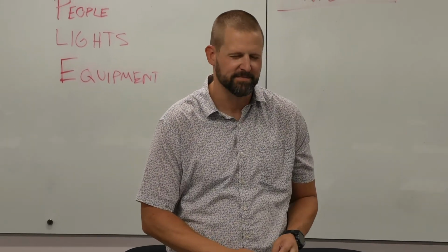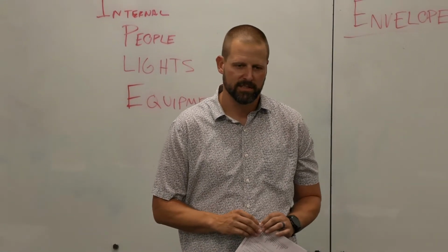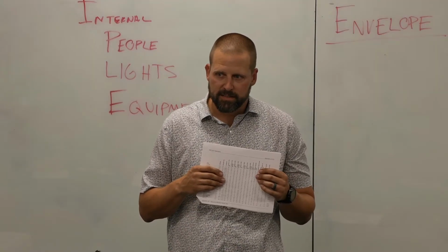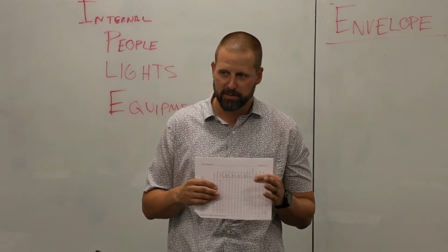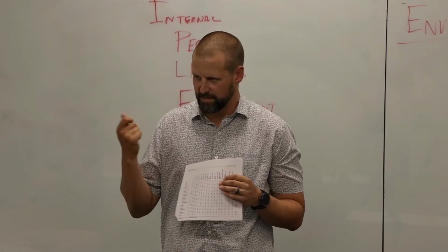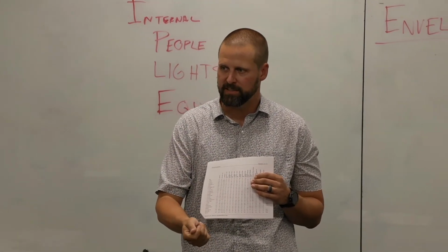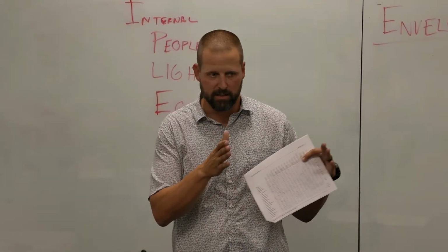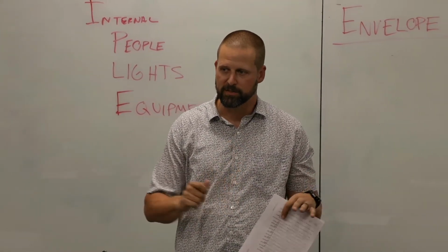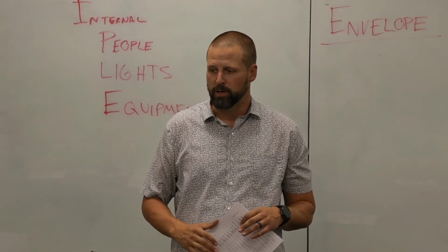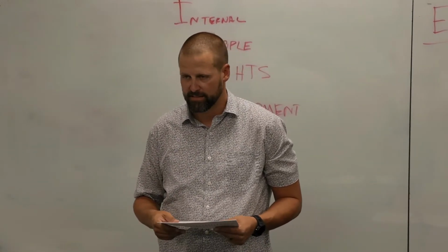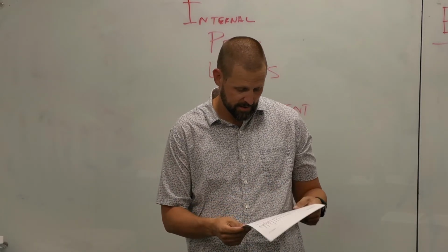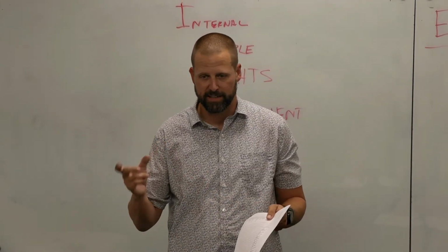One other thing that comes from here, ambient temperature, and this is kind of getting off the load thing. We care about the ambient temperature or the outside air temperature because we suck in outside air and have to cool that down when it goes in the building. That is sometimes handled differently with our heat rejection piece of equipment. So for towers, we have a wet bulb temperature. For a dry cooler or a condensing unit, we will typically either use the cooling dry bulb